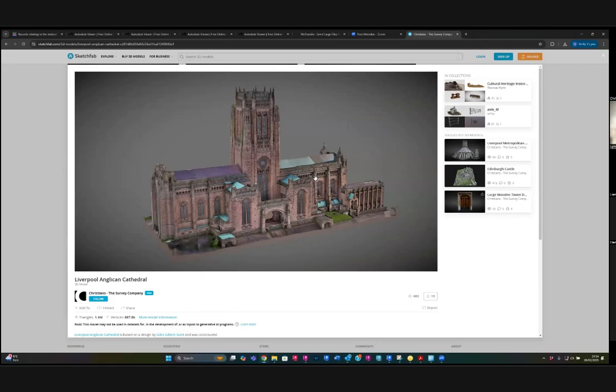So the first thing you'll do is go onto site and put site control in using a total station and GPS to coordinate the site. And then you'll go and laser scan everything. And everyone wants access to the laser scan data, which would be something like TrueView, Trimble RealWorks View, Faro WebShare. There's a few others out there. That's just the point cloud, which will give you your 360 views and you can take measurements.